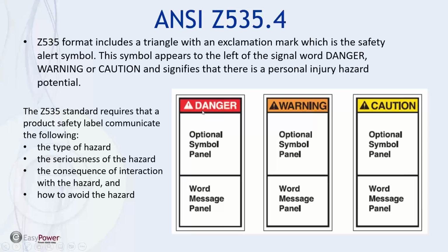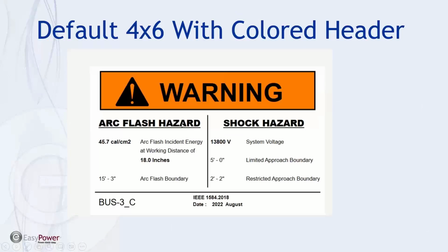And there's a difference between a danger and a warning, both in the colors and in the symbols being used. And when we get to EasyPower, all we give you as a default standard is basically a warning label and the designation for shock hazard and arc flash hazard. That may or may not be appropriate for what your customer requires or for your situation. And I've had some people complain that, well, we're not matching the ANSI standard for higher energy level.